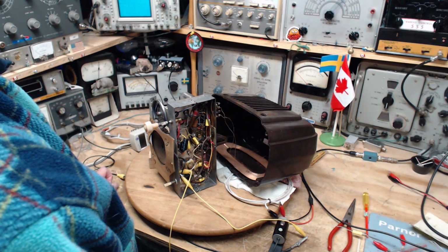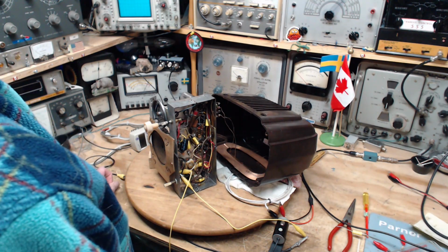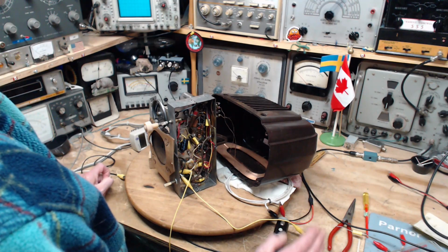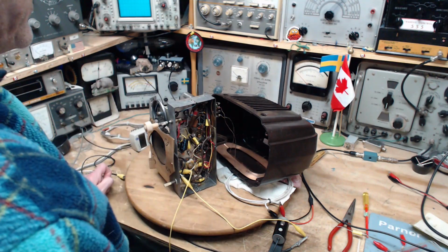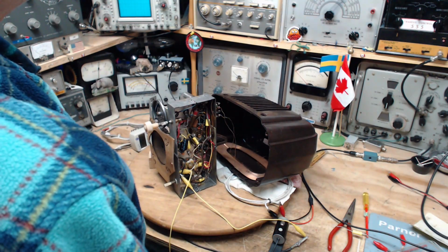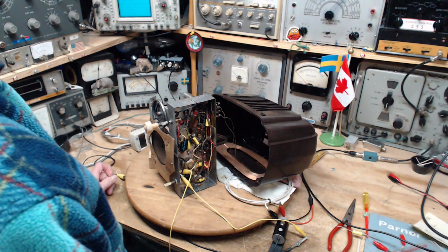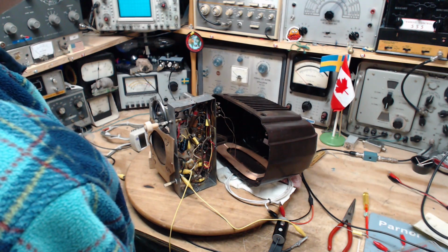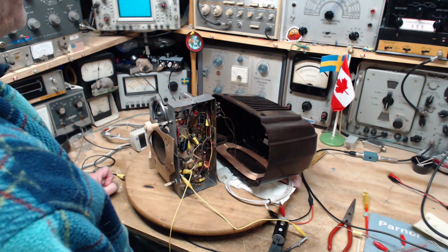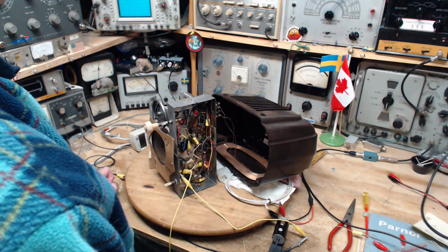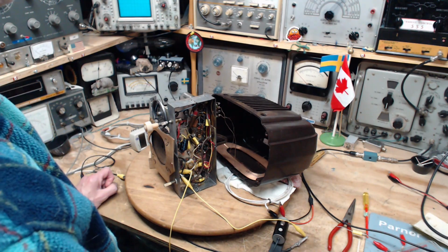And as you tune stations in, there's a heterodyne tone that starts at a high pitch and comes down to 0 when the station is tuned right in, and then as you tune past the tune point, the tone returns. I think that's a strong indication that there's a free-running oscillation in the IF. Another indicator of that is the kind of sound the radio is making. When you tune in a station, say someone's talking, instead of sounding kind of like what I sound like now,